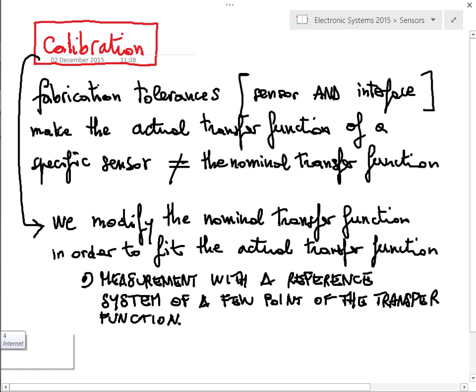Okay, for example, then in the simplest possible case, we know that the transfer function is linear, but we need to adjust the starting point and the ending point. And then if the transfer function is linear, we have a well-fitted line. Okay. This is, for example, what we do. What I do when I'm fitting the tablet here. I'm looking at the right angle, all the angles. Then, assuming that everything is linear, I have the position that is. I mean, I have the sensor that is completely calibrated.